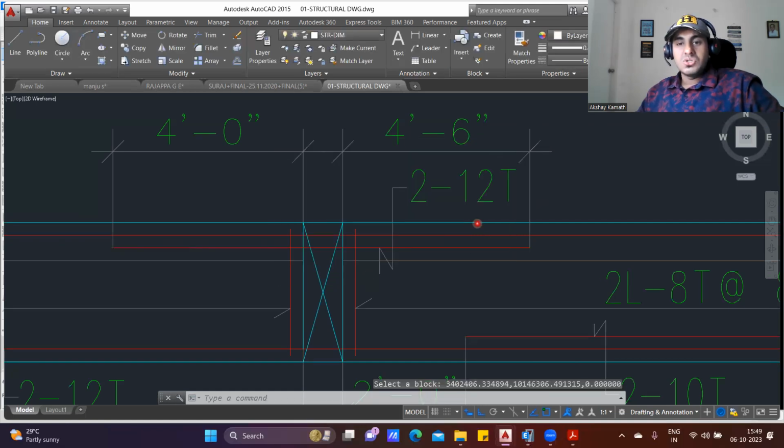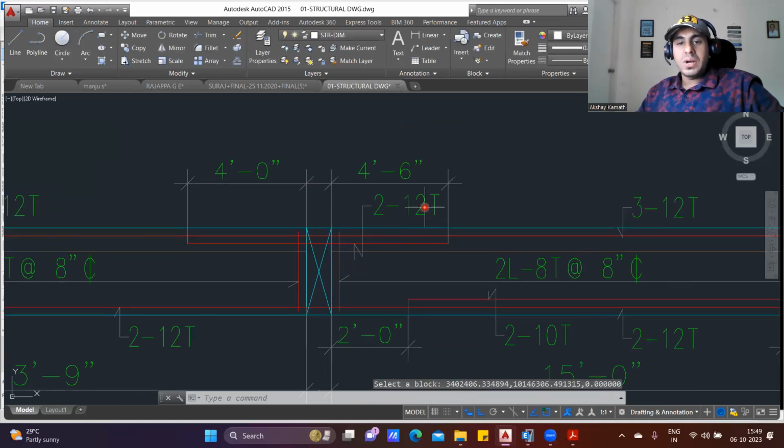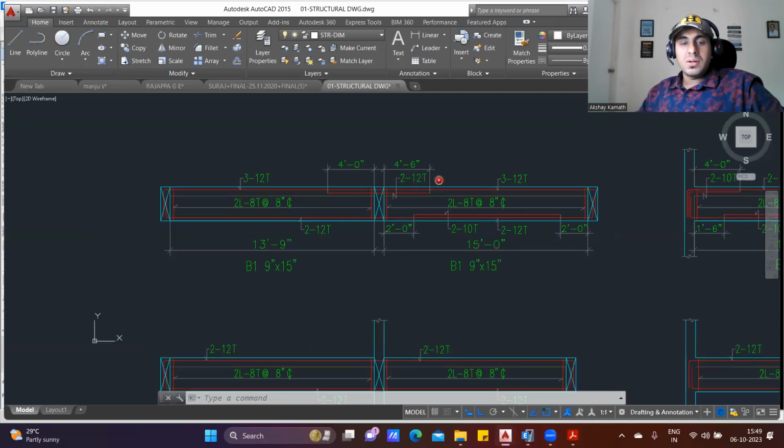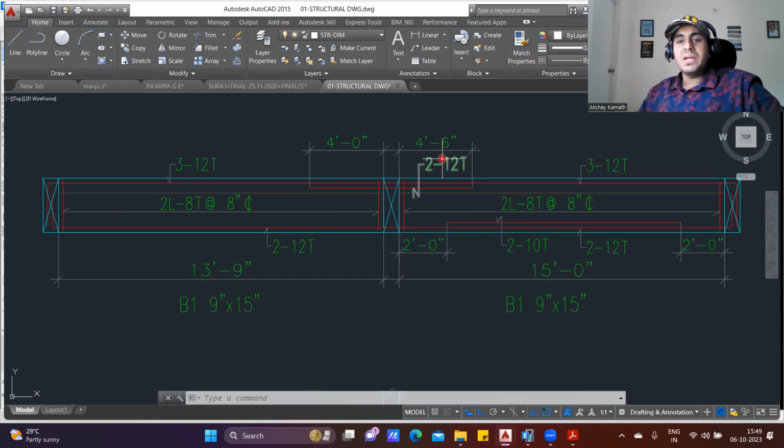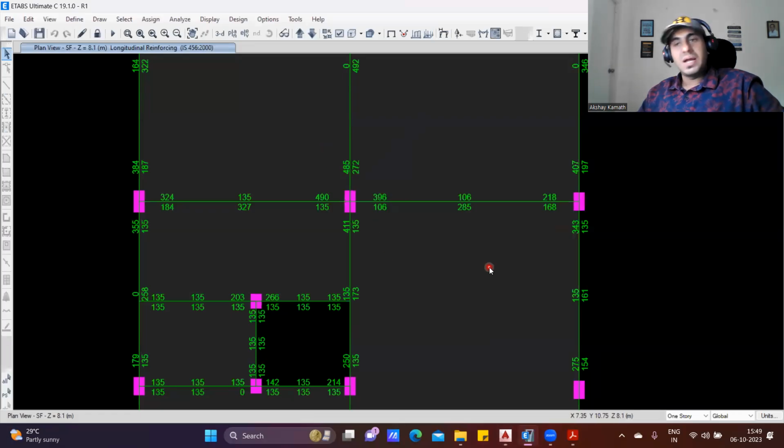Okay. So now you understood. See, I've written 12 diameter 2 bar additional steel, but this steel will go only up to this distance. Got it? The same thing I've explained you. In this way, you need to draw this thing, drawing like this and give it to the site people. But how did you decide whether 12 diameter 2 bar was required, 3 bar was required? That is decided based on the calculation. Understood? For the top, I've explained you.